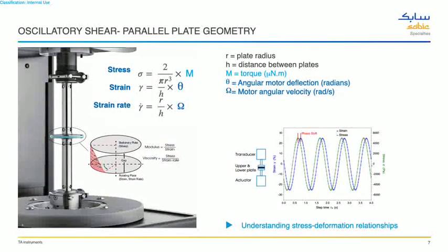The deformation imposed, and the torque, is measured by the force transducer. If you put a strain on the material, it can calculate the stress given by the sample, and then you can calculate the strain rate. Basically we input the deformation strain to the material, and then it calculates the stress given by the sample for a given temperature. So you can back-calculate the material response in terms of how viscous it is and how elastic it is for a given temperature. This is a very powerful tool.